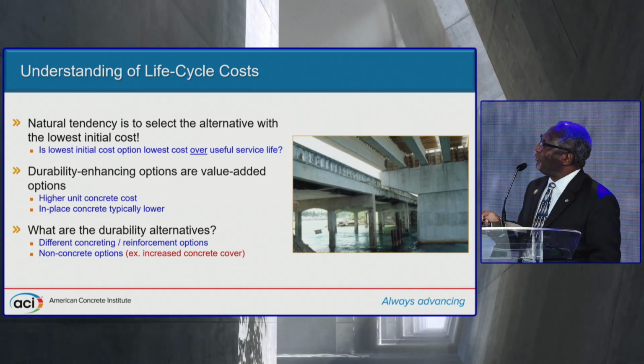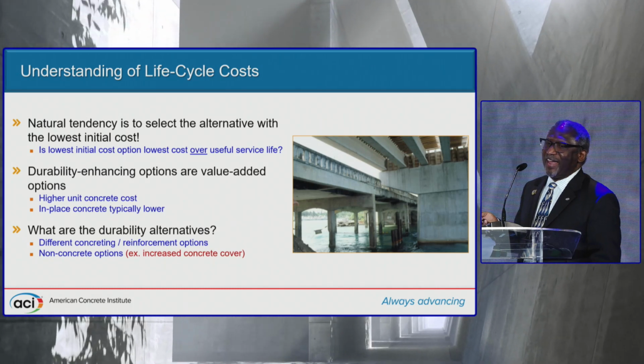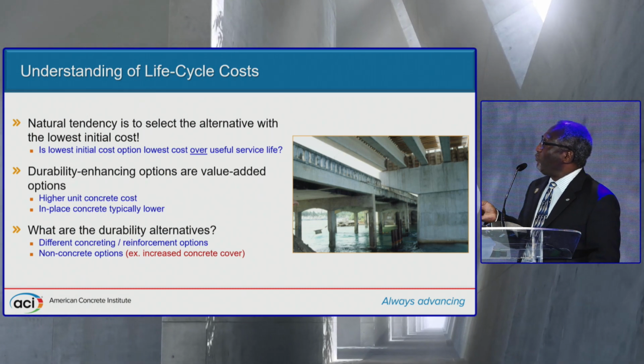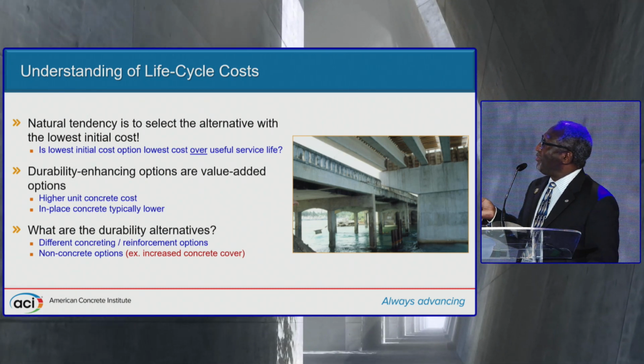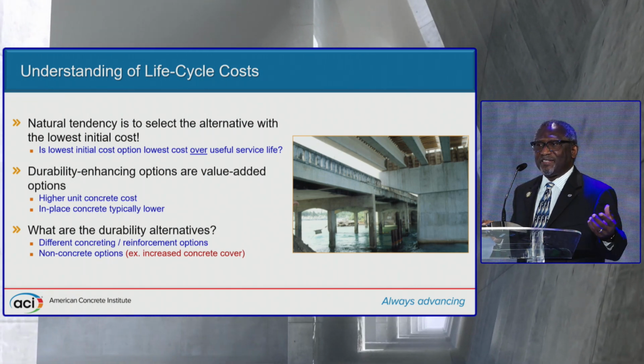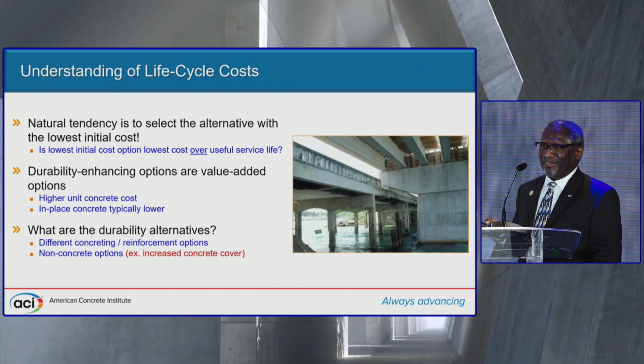The bridge was only about 30 years old and badly corroded and was being replaced. The good thing is, in this particular situation, they didn't want to repeat the same mistake, so this particular bridge ended up having pozzolans as well as a corrosion inhibitor in it.